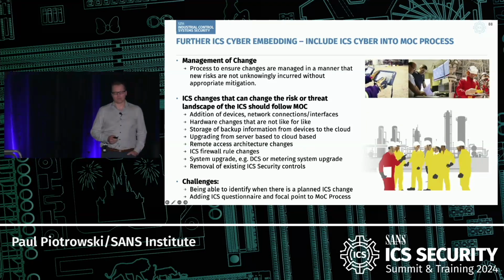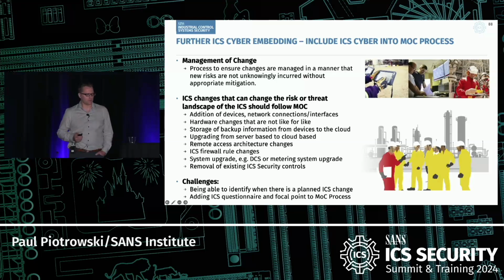So if you're rolling out some kind of tablet, there was a wireless question before, if you're doing tablets, these little HMI tablets using 802.11, you definitely want to do some kind of management of change. You do not want to have these things show up in your environment without your knowledge or without security people being involved in the discussion, to make sure that they're configured in a secure manner and that the architecture is done. Because guaranteed, the vendor and the asset want those things, and they'll do them even if you're not involved. You'll be surprised at some of the stuff that you see when you go to an asset. Where did that come from? Nobody told me that was being deployed.